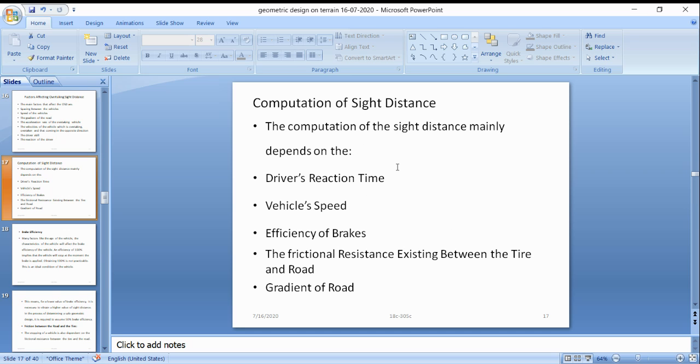and overtaking sight distance. So the sight distance really depends upon the driver reaction time. The first main consideration is the formula we have considered for SSD, stopping sight distance: 0.278 Vt plus V square by 254 into (F plus or minus 0.01 N). That formula we have seen.